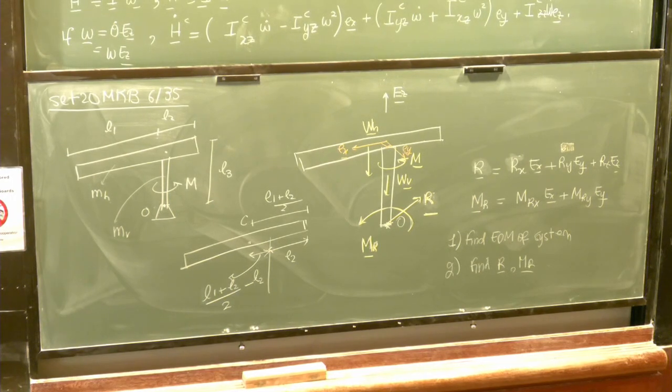We explained it quickly before. Remember, sometimes instead of giving you moments of inertia, they give you radius of gyration. Where does the term come from? An equivalent circular hoop, yes, the moment of inertia of a circular hoop. So how do I calculate the moment of inertia of this system about ZZ? I_O,zz is going to be m times the radius of gyration squared.